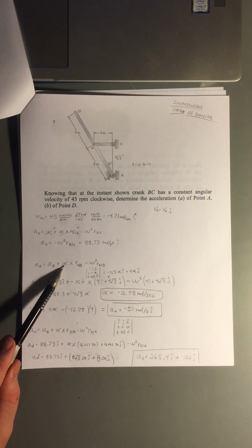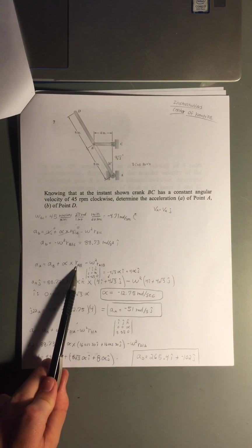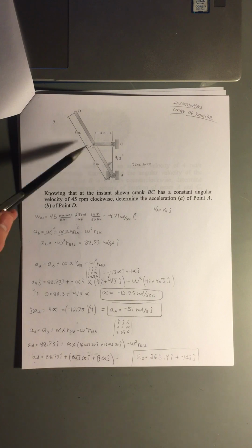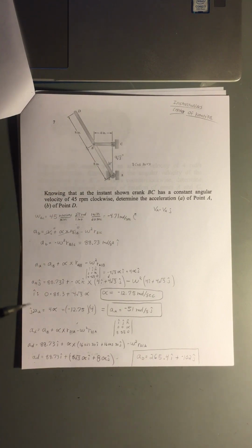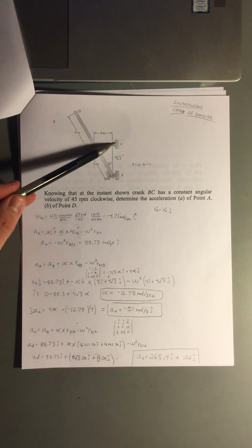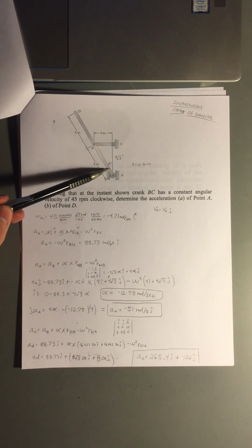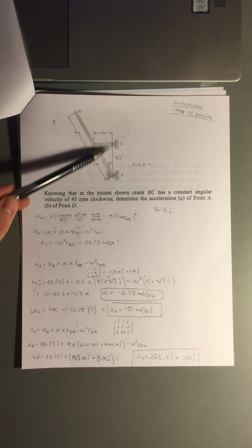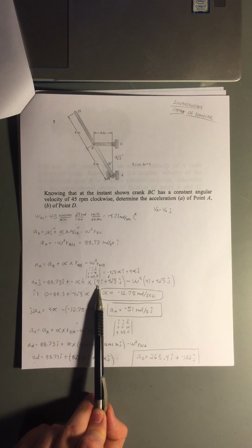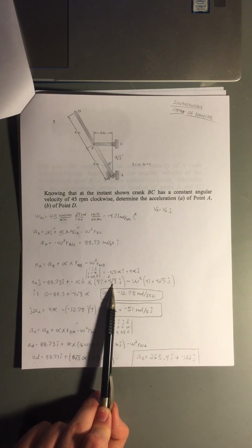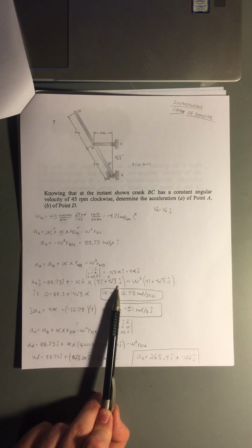We don't know alpha yet, but we can find this distance here between A and B. And so what I did is broke this into components. So we have these dimensions here. So using the cosine of this angle in here, we can find the height in the j direction. And so the distance between A and B is 4 I hat plus 4 root 3 j hat.